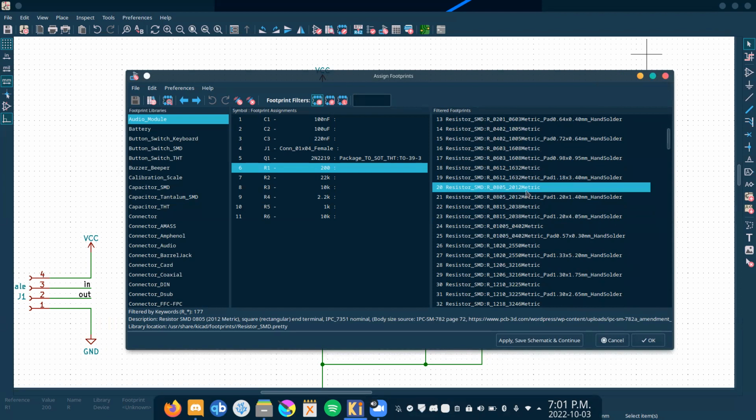Actually, that's not even true. The other one here is 1.2 millimeters by 1.4 millimeters, and it's called a hand solder component. When working with the team, you probably want to pick hand solder components because they're a little bit bigger and the pads will be bigger.